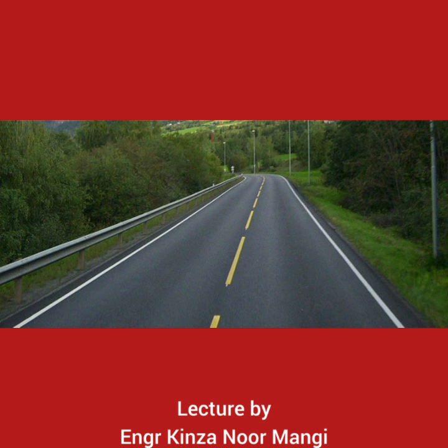Starting with the carriageway. A carriageway generally consists of a number of traffic lanes together with any associated shoulder, but may be a sole lane in width. Traffic lanes are those lanes on which traffic can move freely without any restriction. The carriageway is divided into a single carriageway and a dual carriageway. A single carriageway has one carriageway with one or two or more lanes together with associated pathways and road verges. A dual carriageway has two roadways separated by a central reservation.